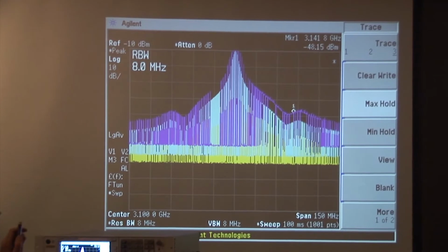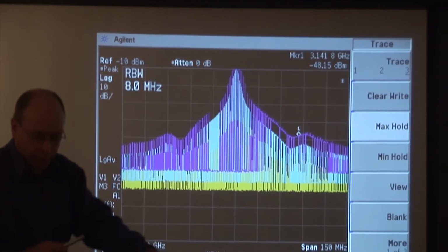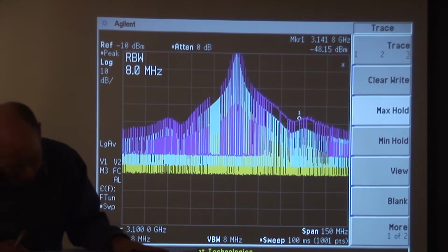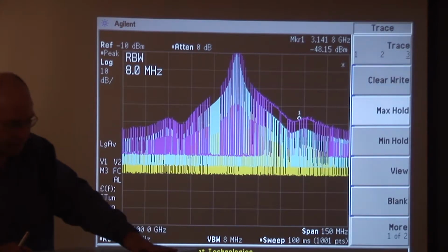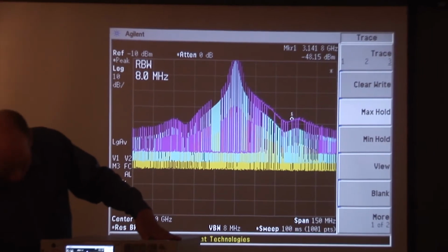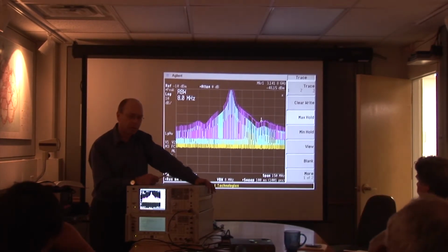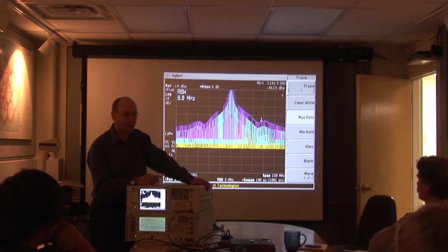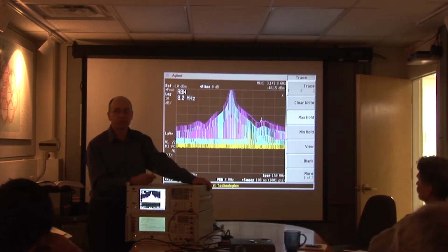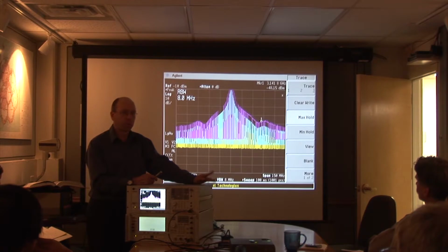First, actually, I will explain this. So, we have two boxes here. The upper box is a spectrum analyzer, and we've used this analyzer for some previous measurements. There's nothing unusual about it compared to other types of spectrum analyzer. The lower box is a vector signal generator, and I've kept it turned off up to this point because it has a cooling fan that makes a loud whine that we can pick up on the tape. But the vector signal generator has been programmed by one of our engineers, Brent Bedford, to produce 1,000 pulses per second with a 1 microsecond pulse width for each pulse.